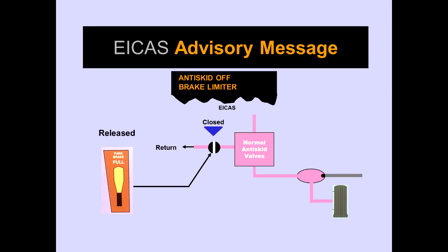The EICAS advisory messages ANTISKID OFF and BRAKE LIMITER are displayed if the parking brake handle is released and the parking brake valve does not open.